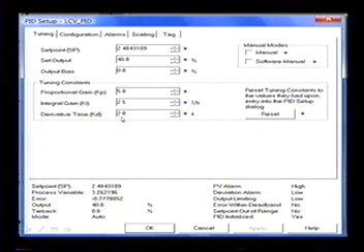So if you wanted a proportional controller, you would go ahead and set this to 0 and this one to 0, and you'd leave this to some value greater than 0, and you'd have a proportional controller only. And remember the formula on that was KP times E, the error. So if you set this to a little integral here, you'd have a PI controller. PI controllers are good for a lot of things, actually. Speed control for like generators and what have you.